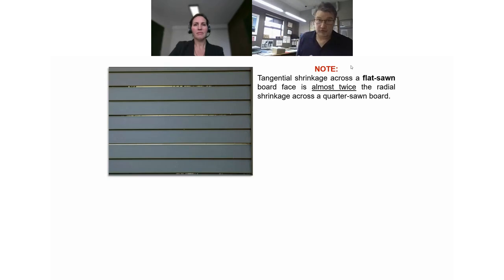You just got to allow it to move, and that all comes into the design. But this is a classic. This picture is from a house that was painted white for 60 years, and then somebody decided, from a fashion point of view, to paint it a dark color. And of course, within a short period of time, now dark colors, we're not going to get into it too much, but they absorb a lot more infrared spectrum, which is your heat generating part of the sun's rays. And all that does is dry them out.